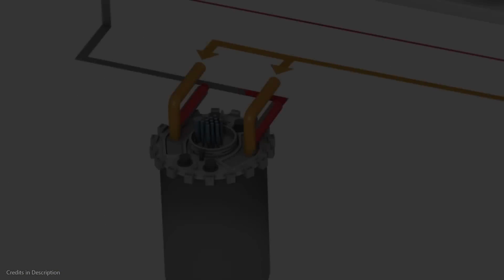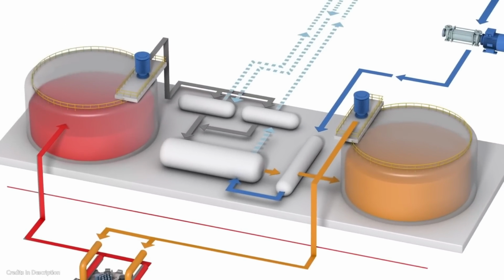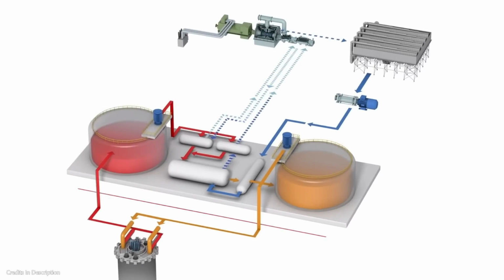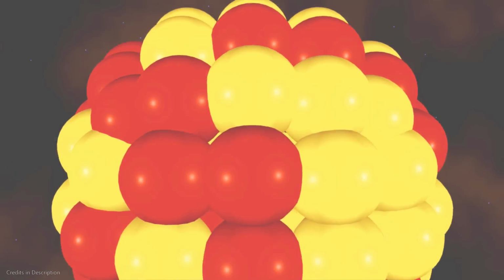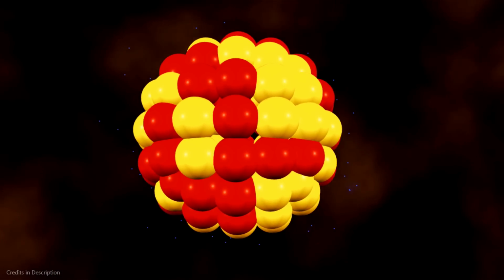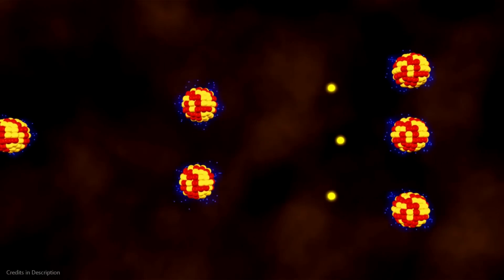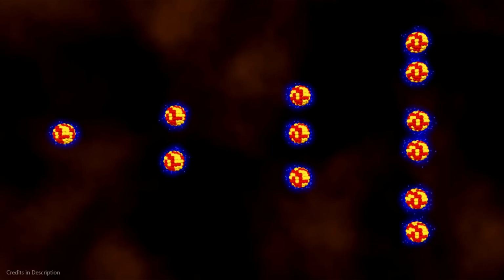Nuclear reactors, on the other hand, utilize a controlled nuclear chain reaction that can be adjusted to generate heat, which can then be used to produce a large amount of power. This makes reactors more suitable for large-scale power generation, but they are also more complex. Most of these are thermal neutron reactors. This means that the neutrons must be slowed from high speed to low speed, also called thermal, for them to be absorbed by the target isotope.